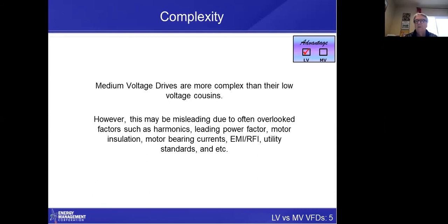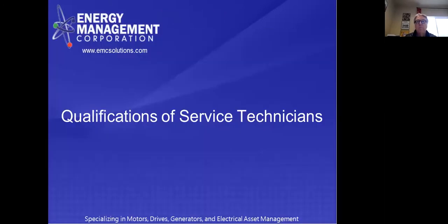And you notice there's a check mark on low voltage, and that means, in my opinion, low voltage drives are less complex and therefore they have the advantage. However, this may be misleading because there are other factors when you use low voltage drives that don't necessarily apply to medium voltage drives, such as harmonics, leading power factor, motor insulation, motor bearing currents, and so forth, which we will get into in this presentation.